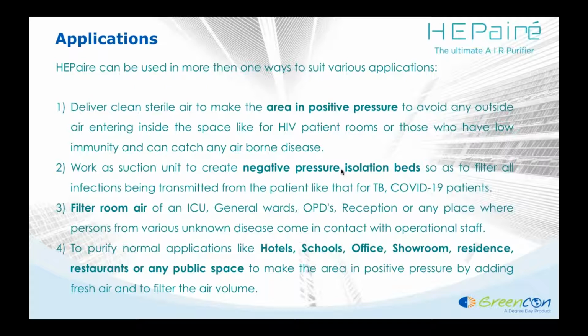You can connect a fresh air port at the suction of the machine to make the area positive pressure. You can utilize the room or the bed suctions and feed it into the suction of the machine and convert the area into a negative pressure isolation bed.